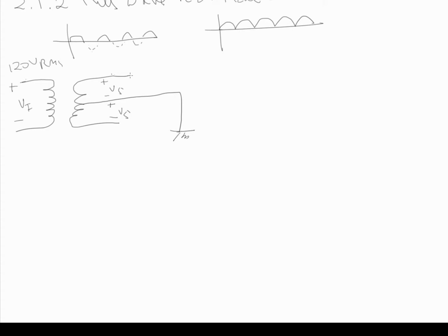And then we're going to use two diodes. So here's one diode, and it's going to a resistor. And then we have the other diode down here on this end. It's not going to connect to this line, so we'll just drop it over, and it's just going to connect up there. And then this is going to be our V out plus minus. And like I said, this is a center tapped transformer.